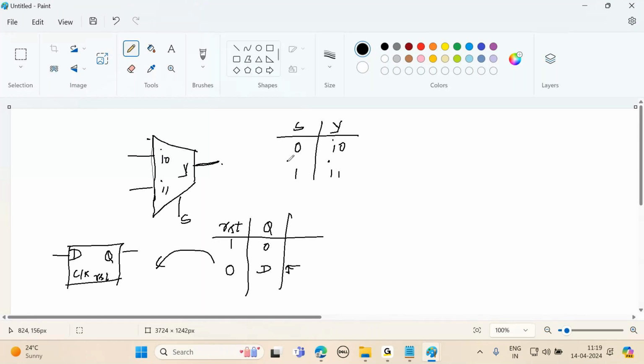This is the behavior of your mux. The truth table you have written in your UG classes is nothing but the behavior of your circuit, right? So defining any circuit through its behavior is easy, but defining it through its internal structure is difficult. So with the programming languages we have defined, we describe every design through its behavior. I can define this mux easily using an if statement. If select equals 0, assign Y equal to I0, else assign Y equal to I1.